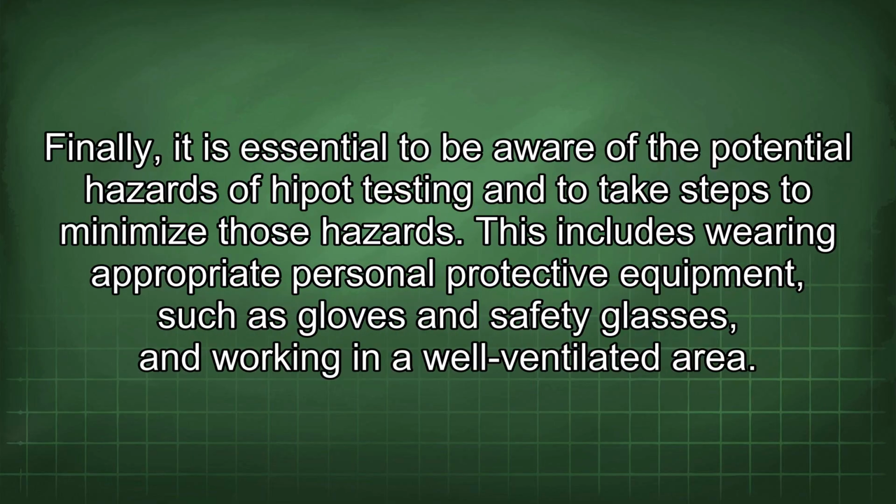Finally, it is essential to be aware of the potential hazards of Hipot testing and to take steps to minimize those hazards. This includes wearing appropriate personal protective equipment, such as gloves and safety glasses, and working in a well-ventilated area.